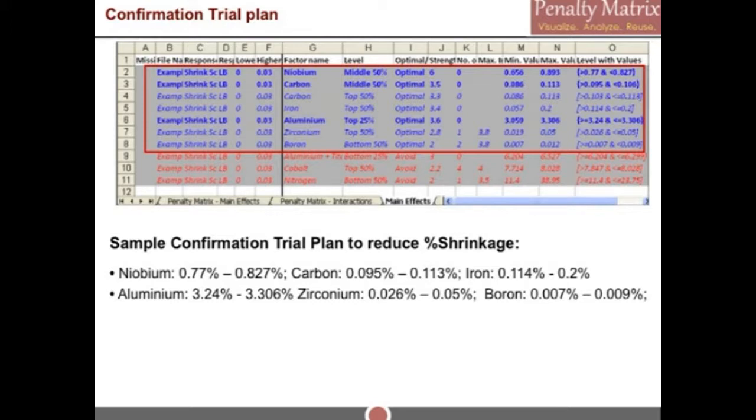So this is what should then happen in the quality control meeting to certify that decision and instruct operators to start tweaking your post-process. You are making several changes at the same time. Now this is just chemistry, but it can go to mold parameters, operator settings, furnace, and you start testing your hypothesis. But it's different from the design of experiment philosophy. You cannot do DOE on this, and also the ranges here are quite small because it's a fine-tuning of your process.